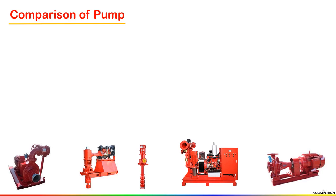If I talk about the maintenance and installation, which is better? Remember, the horizontal centrifugal pump is easy to maintain and install. Why? In a horizontal centrifugal pump you can just open the half casing and do maintenance and all. But in a vertical centrifugal pump, due to its compact design, it is not easy to do the maintenance, okay.